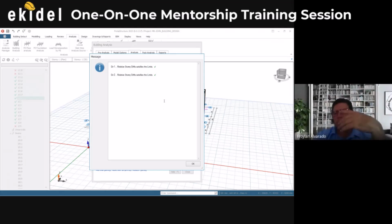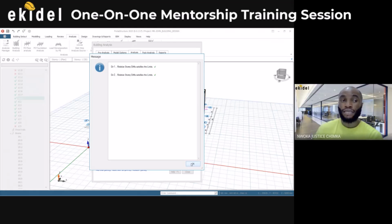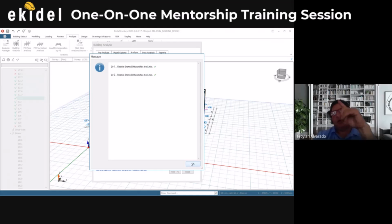I was just wondering in terms of the roof itself, like when you model a roof, that it automatically compensates. Yes. Once you model for the roof, it automatically transfers the load to the roof. No need to add any load again on the roof beam. It will just transfer the load to the roof beams, and then continue from there. But does it analyze the truss then?